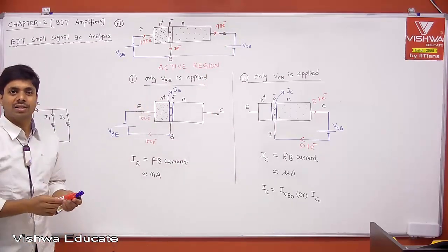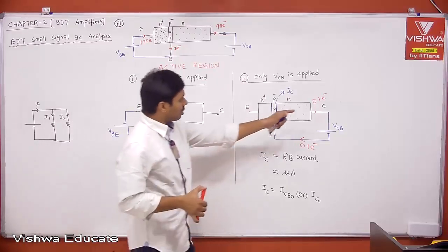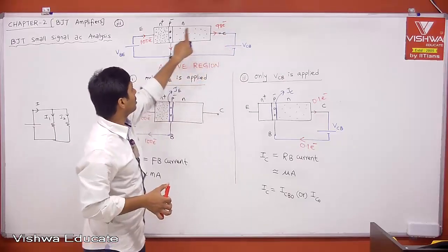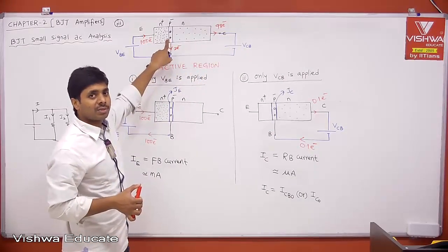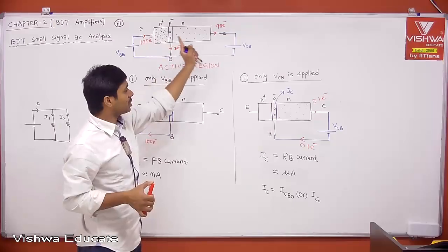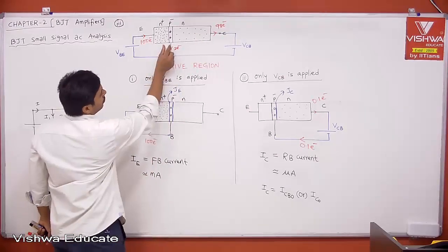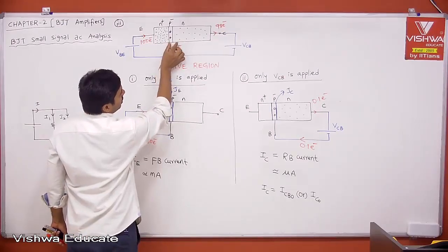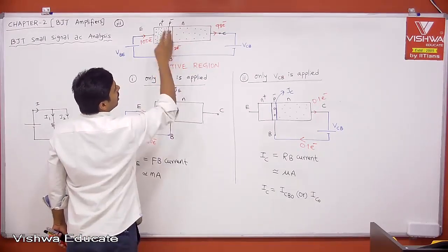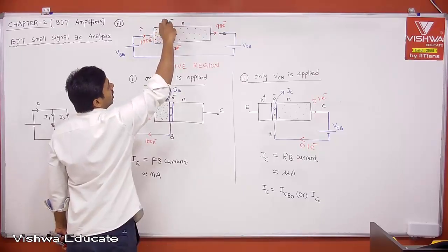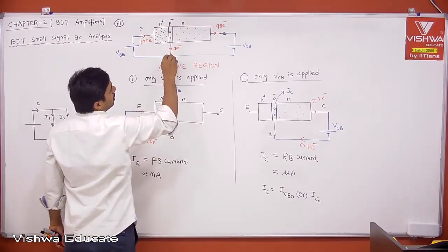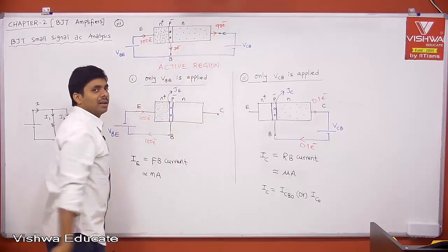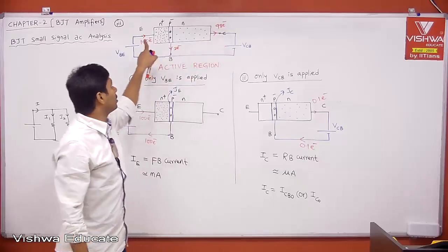This is transistor action. What are we expecting through the collector? We are expecting almost zero current, right? But we are getting collector current almost equal to emitter current. That is because of transistor action. To get this transistor action, the size of the base is very small. Let us say the size of the base is not very small. If the base size is more, then it will see more number of holes. Then more electrons entering the base will come out of the base, and only the remaining electrons will enter the collector. Therefore, instead of 98, maybe 90 and 10. Then in that case, your collector current is not equal to emitter current.